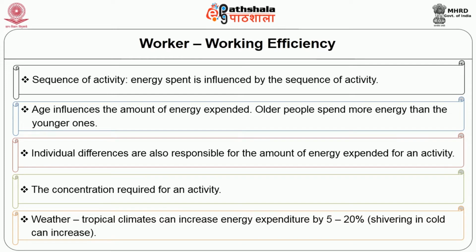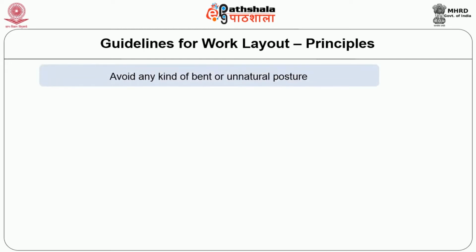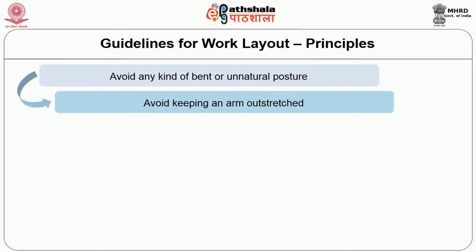What could be the guidelines for workplace layout, and what are the principles to be followed? Under that, the first one is to try to avoid any kind of bend or unnatural posture. Second, avoid keeping an arm outstretched always.